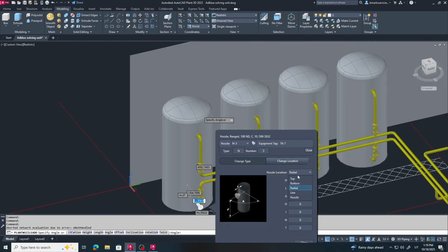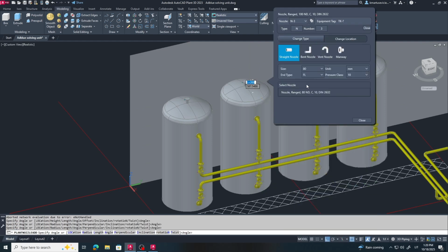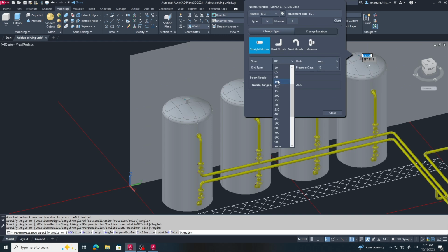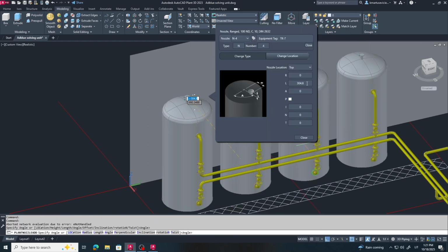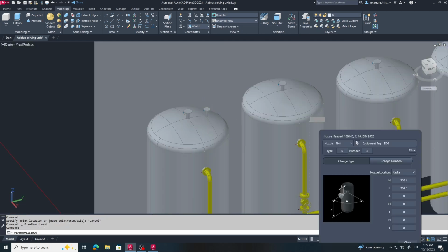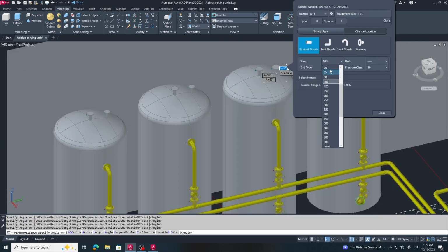Now I'm working on the top nozzles of the AdBlue storage tanks. These vessels are atmospheric, which means they're not pressurized, so each tank needs a vent pipe at the top. The vent pipe lets air escape when the tank is being filled and allows air back in when product is being pumped out. Without proper venting, the tank could deform or the pumping process wouldn't work correctly.